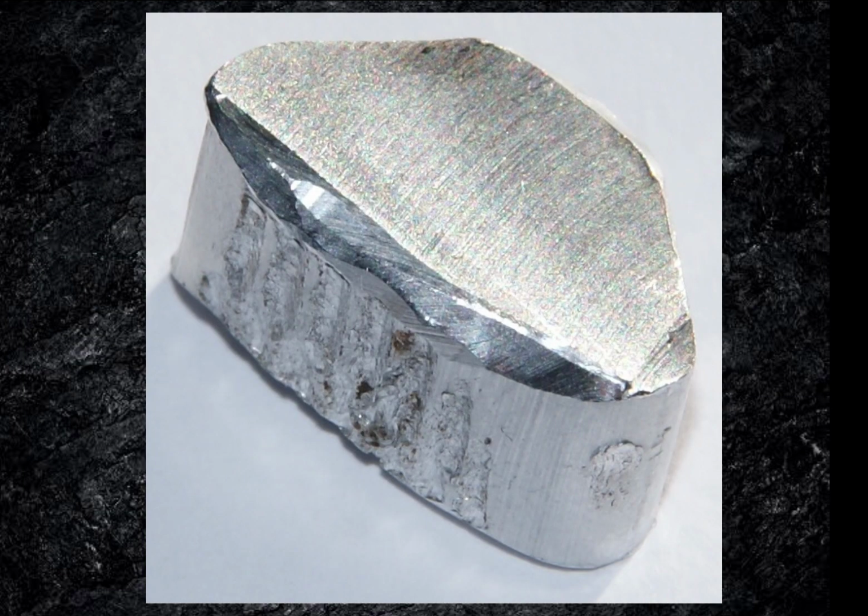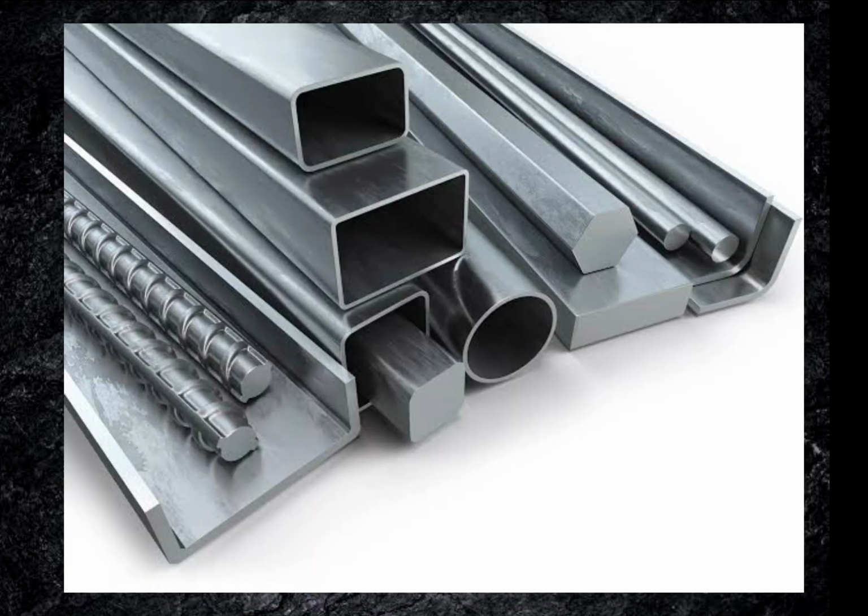It has a low density, is non-toxic, and has a high thermal conductivity, and it can be easily cast, machined, and formed. It is also non-magnetic and non-sparking. It is the second most malleable metal and the sixth most ductile. Aluminum is a good electrical conductor and is often used in electrical transmission lines. It is cheaper than copper, and for weight, it is almost twice as good a conductor.